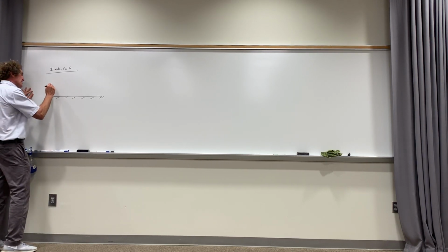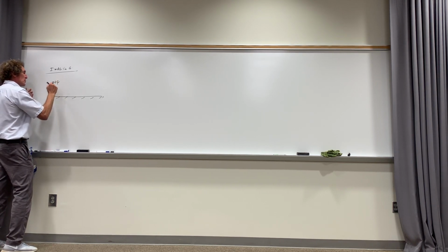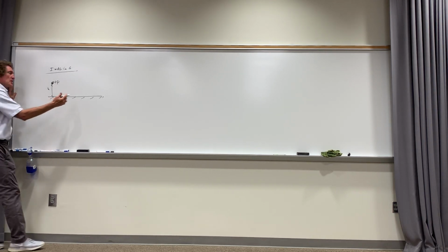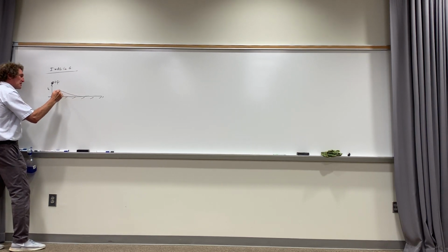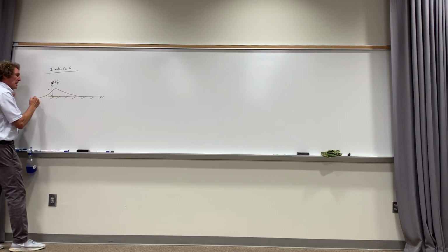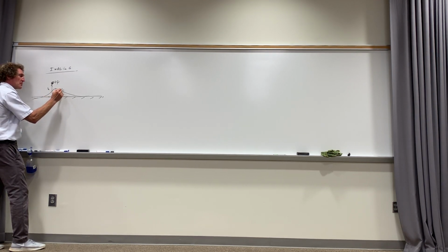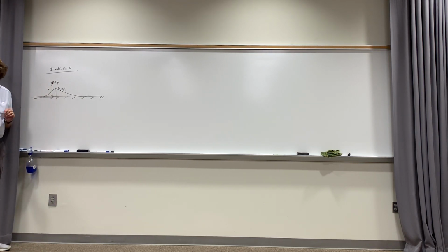So if I have something at a height h above the ground plane and I put some charge plus q, here's what happens. That plus q charge will attract negative charge, and if you actually look, it will look something like this. In graduate school, we have to get the profile of that. That would be the charge density, rho s, only it would have a negative value. It would be the magnitude of the charge density. It's a peak right below there, and that should make sense. It would attract negative charge.